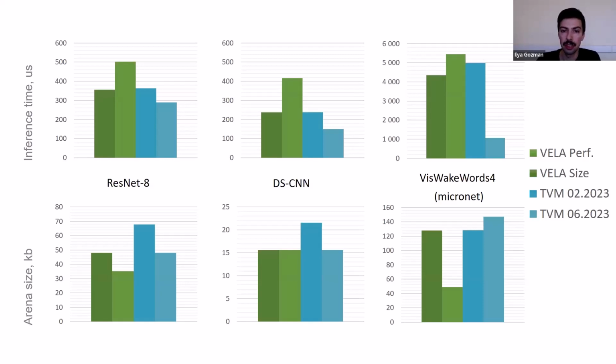Let's delve into some results from specific models. In our work with TVM, we've always used TF-Lite and ARM Vela as our reference points, as a benchmark compiler for the NPU. To this end, we have set our benchmarks against them for a comprehensive comparison. It's important to note that in some instances, performance enhancements come with a trade-off of increased memory usage, as observed in the case of the last network on the slide. This occurred because we needed to block the remove concatenates pass under specific conditions in TVM, which were necessary for this particular implementation.